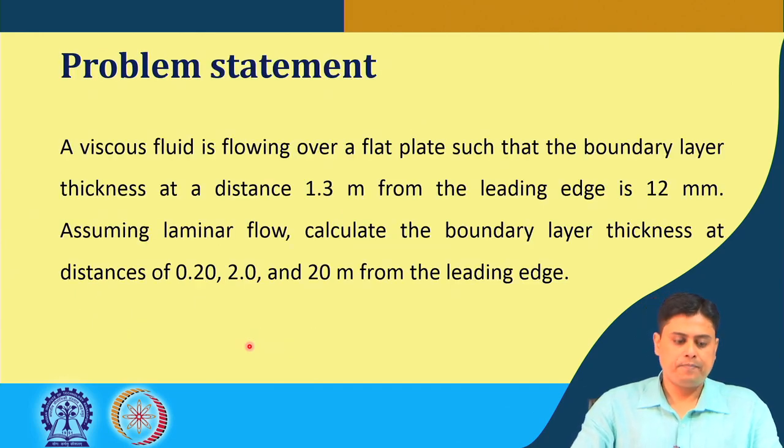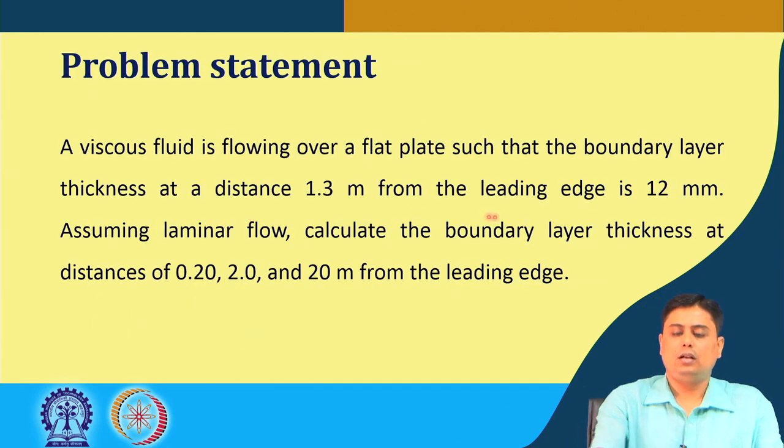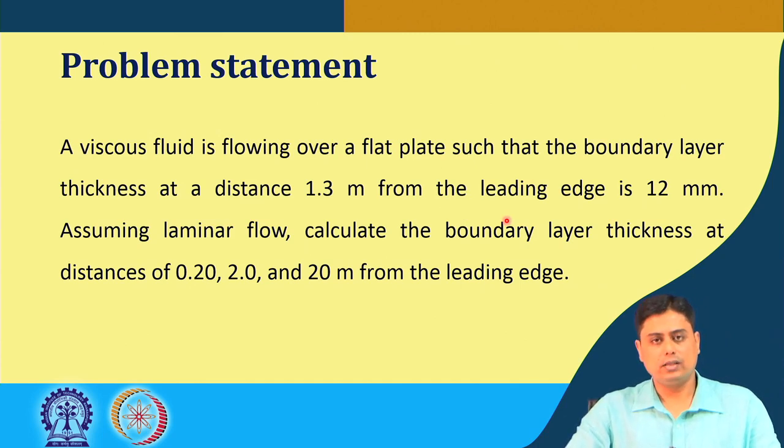Once again, we have just played with the concept that boundary layer thickness for laminar flow varies with the square root of x, even without knowing any particular correlation.